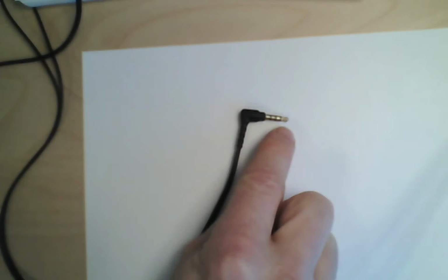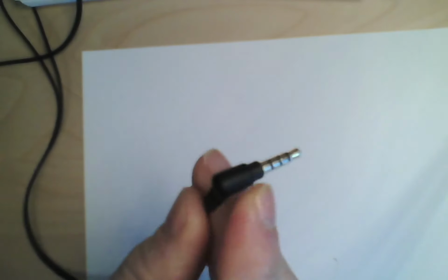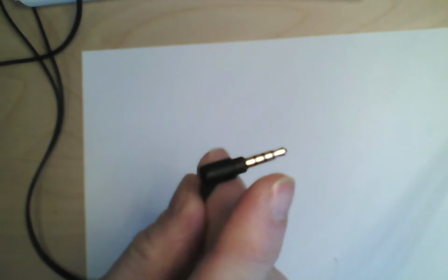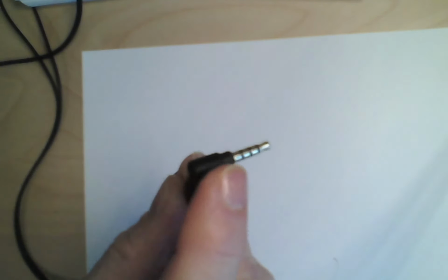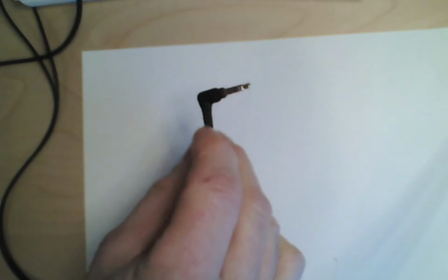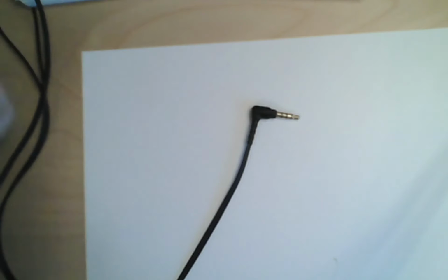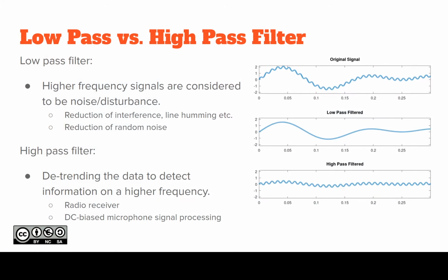You have a signal only for the microphone, and then two of those rings are for the loudspeakers left and right, and then ground. But still you have the microphone signal and this information about the buttons, so there must be some smart way of checking if the button is pressed or not.